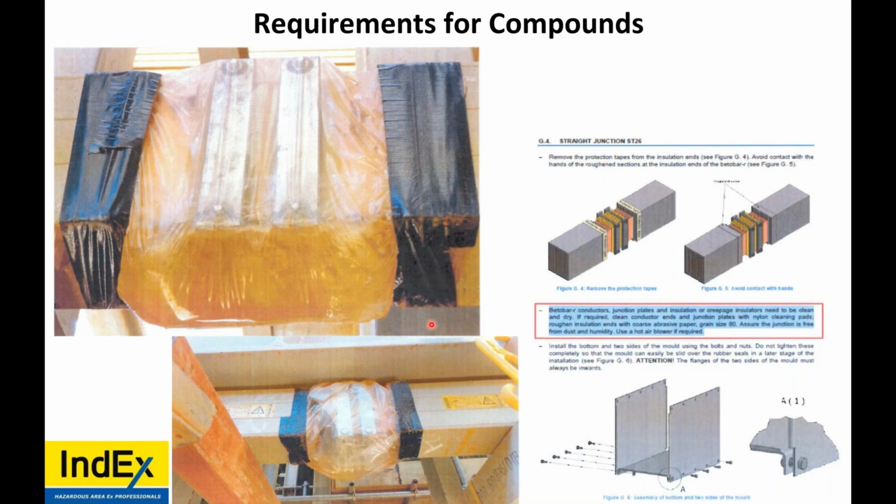Now, did they do as the manufacturer said, where you're supposed to drain it, use a sandpaper of grain size 80 and roughen up the joints and then blow it with a hot air blower? Of course they did not. Do humans read the instructions? Of course they do not. This is why human factors are 99.99% of all failures. This is a case in point.